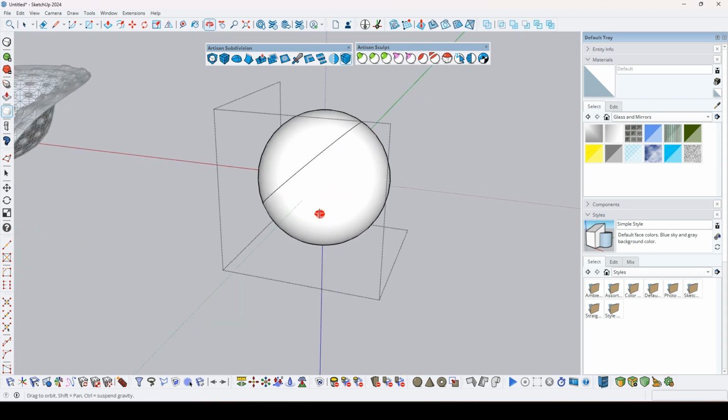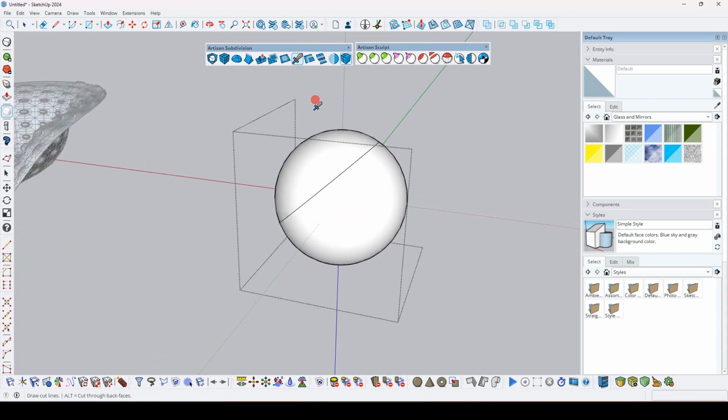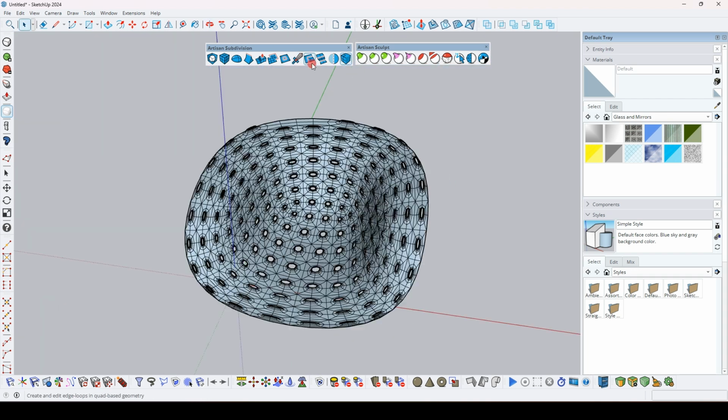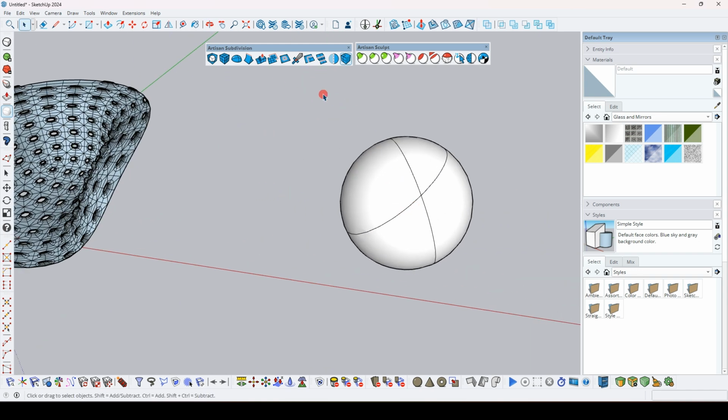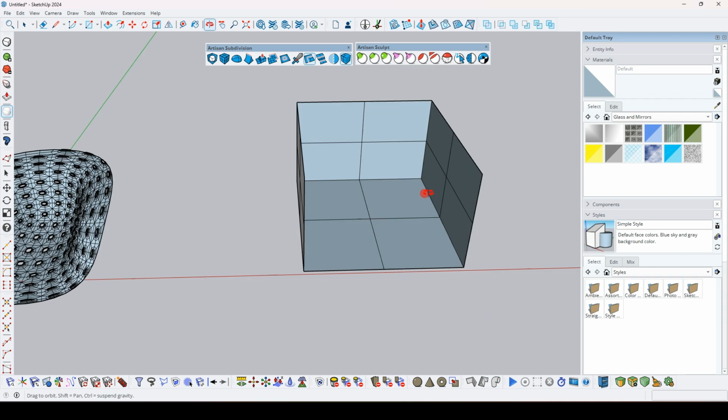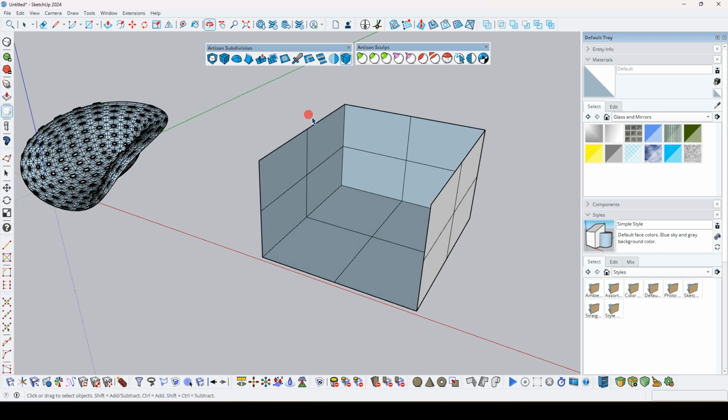If you want to do multiple cuts, you can do it. Just click, drag, press alt, and click. Okay. Now there is another tool that is called a loop tool. So loop tool, how does it work? If you want to create a loop line amidst of this line, then you have to just drag your mouse over the line and then create a loop subdivision. Okay, just like that.